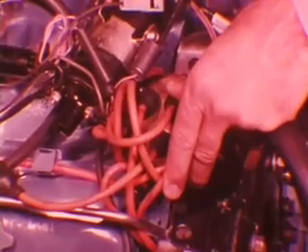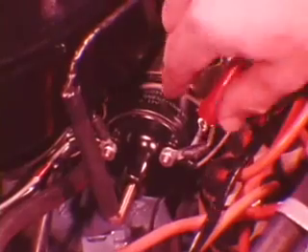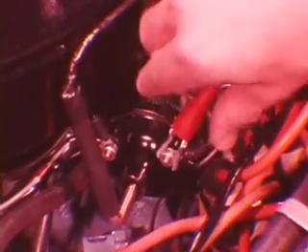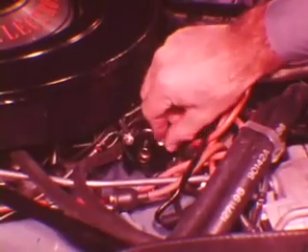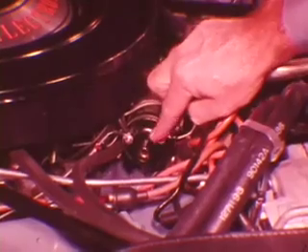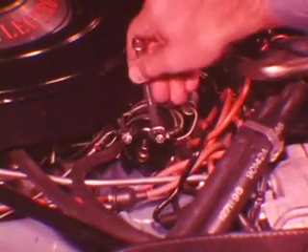But here's a point to remember. Whenever a fault is found and corrected, you must stop and restart the diagnostic sequence from the beginning at code 1. Fault code 28 could indicate a fault in the analyzer, or it could be caused simply by a faulty connection of the red clip to the coil positive terminal. Fault code 35 says coil resistance out of tolerance. Again, it may be a question of connections or wiring. If these check out okay, replace the coil and start over from code 1.